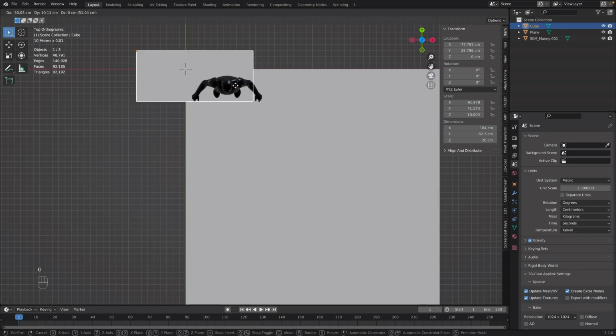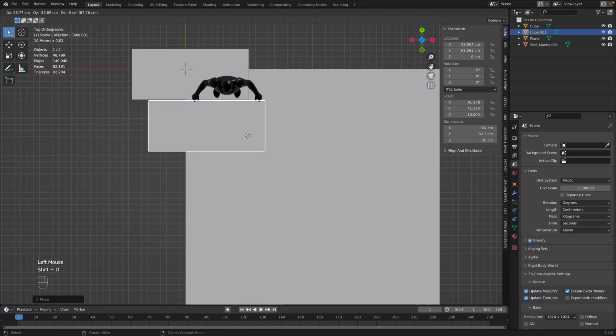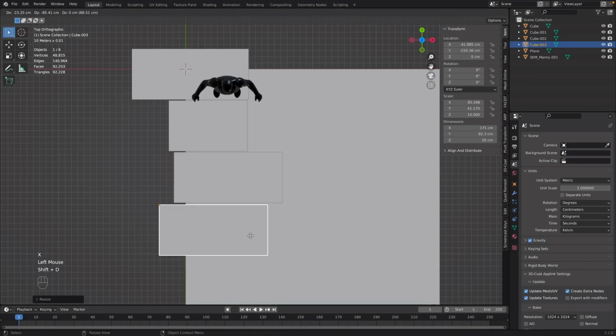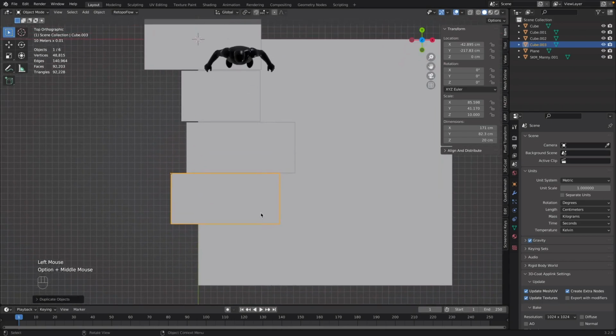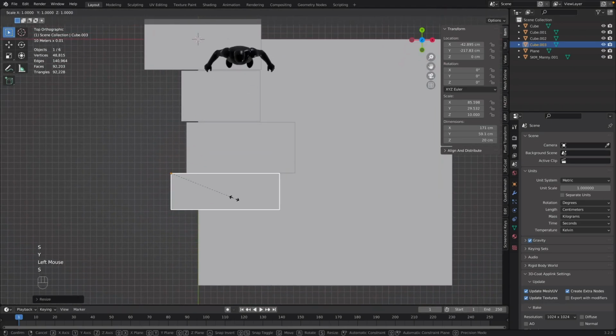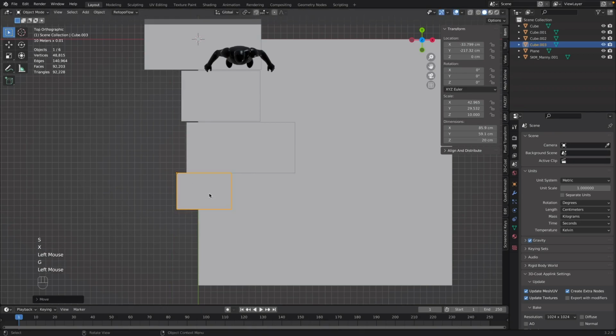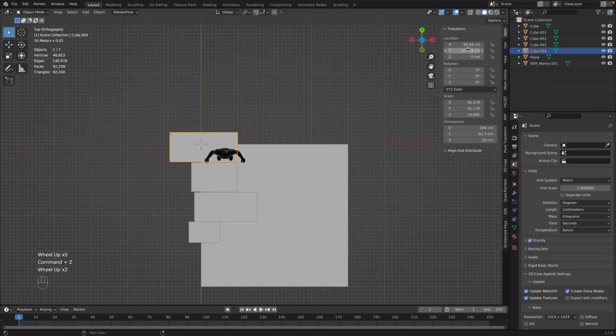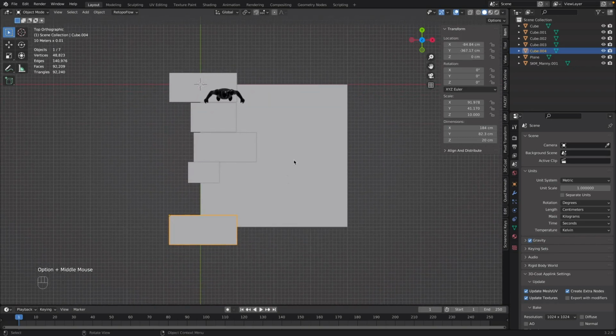You don't have to make them exactly the same way I did or the same size. Just play around with sizes and go with your gut. Make them what feels right for you. Having the pivot point in the corner helps with positioning and duplicating our pieces in each of the 4 corners. I just added 400 centimeters to our X or Y position, and that automatically moves the pieces to where the seam will be.